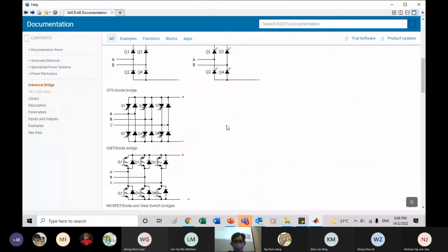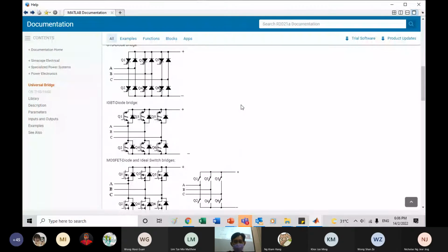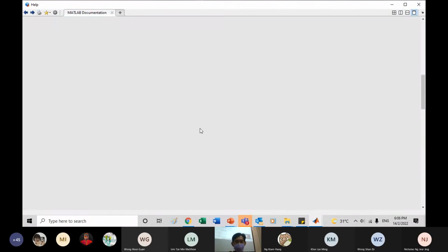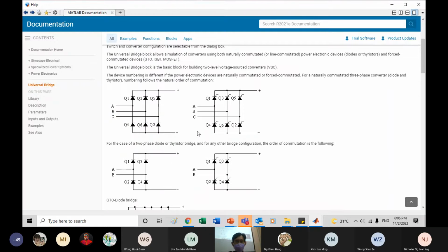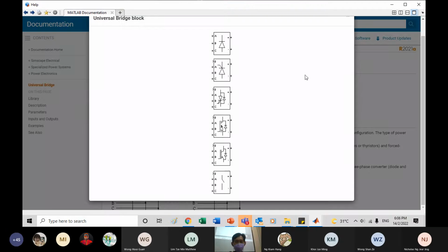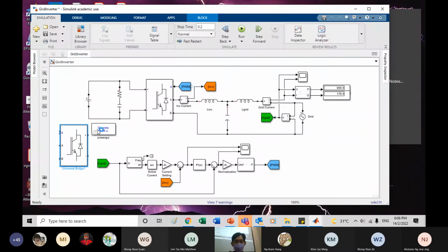It will show you whether it is a diode, thyristor, or transistor, and so forth. So this is how you can change the configuration of all this. You can see inside the chain, and of course for the bridge you just change depending on whether you want to use MOSFET or IGBT. So this is a very convenient way for you to test your idea. And then when you want to really implement the real inverter, then maybe the transistor you buy, then you can do the detail.